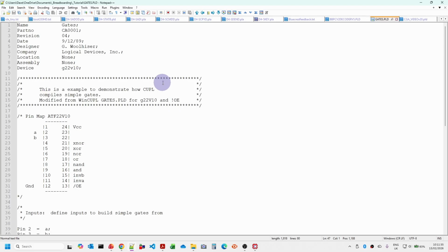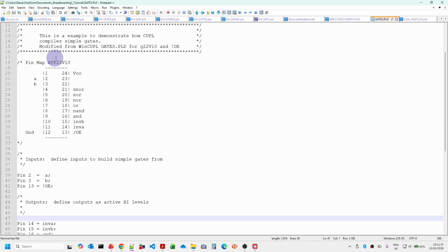Comments are pretty much standard sort of comment syntax. I always tend to put a chip layout on here. I just find it helps to visualize what's going on and to help lay out things in the optimal way. We need to say which label we're associating with each of the pin inputs. You can also see we have an output enable here as well, and the output enable has an exclamation mark by it, and what that basically means is that that will be active low.